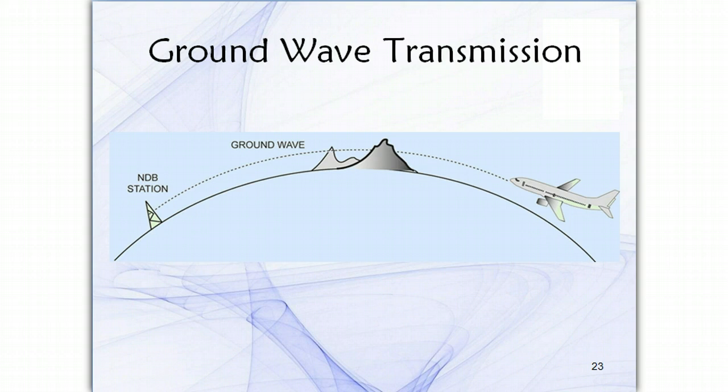The ground wave: these are the lower frequencies, mainly between 30 and 3,000 kilohertz. These are the MF and LF spectrum, and have the property of following the curvature of the Earth via ground wave propagation. The MF and the LF travel great distances. HF and VHF travel relatively short distances.